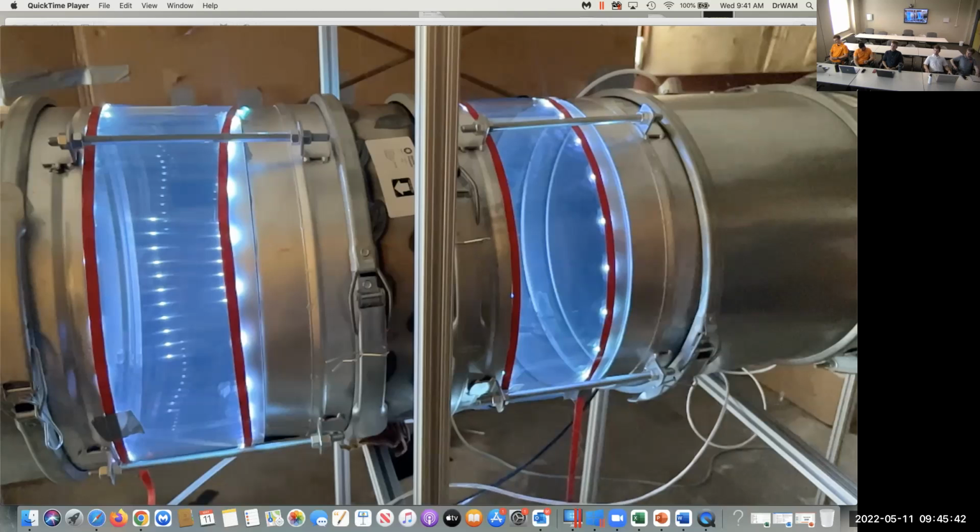Well, if we put it there, Gary, the duct and the evaporator coil is wet because it's dehumidifying the air. The ions would do a great job of cleaning the coil, but then they would be dissipated and no longer available for doing what we want to do. Okay, I didn't think about the coil.